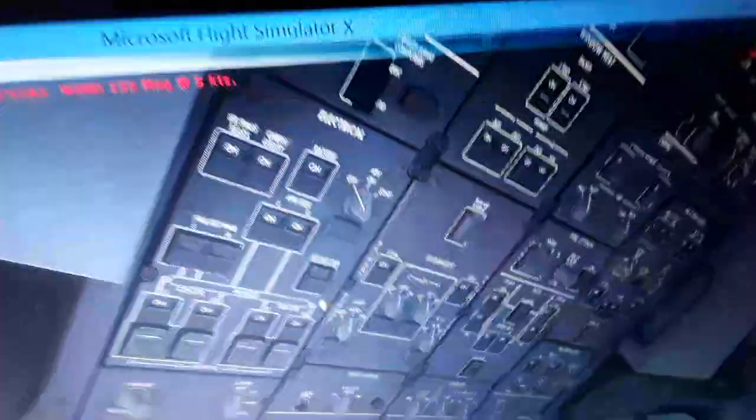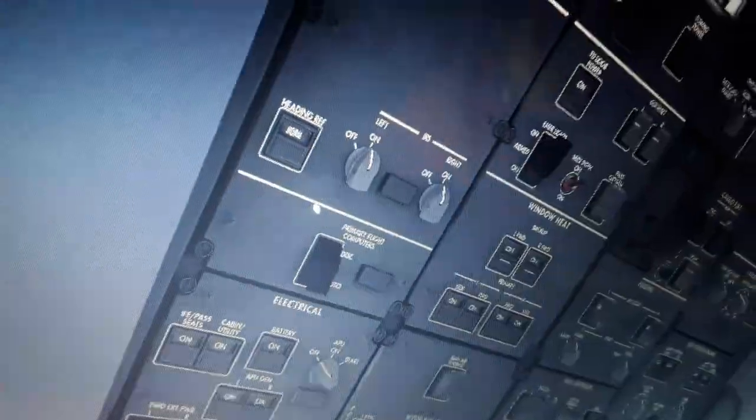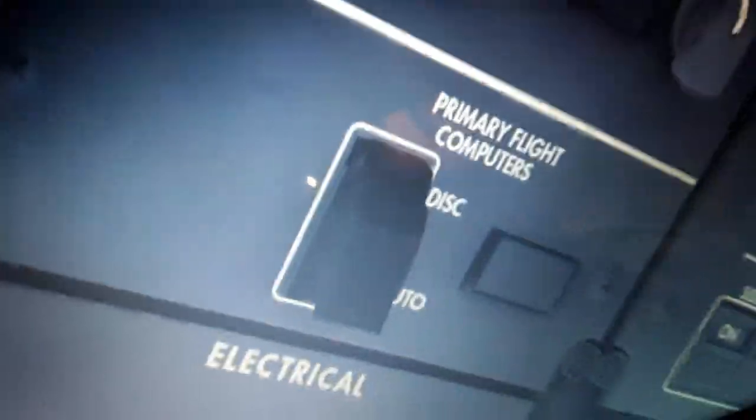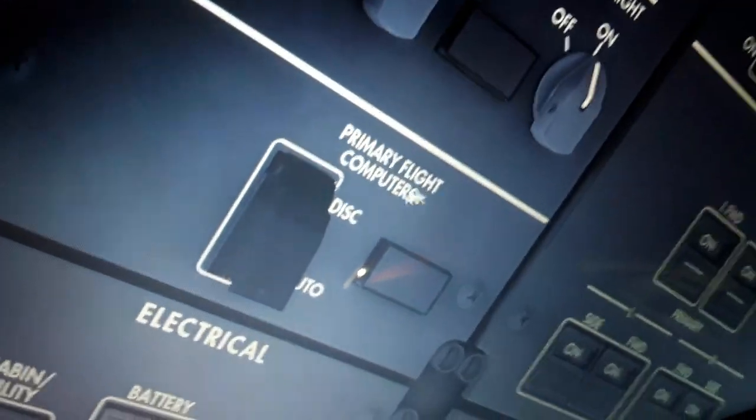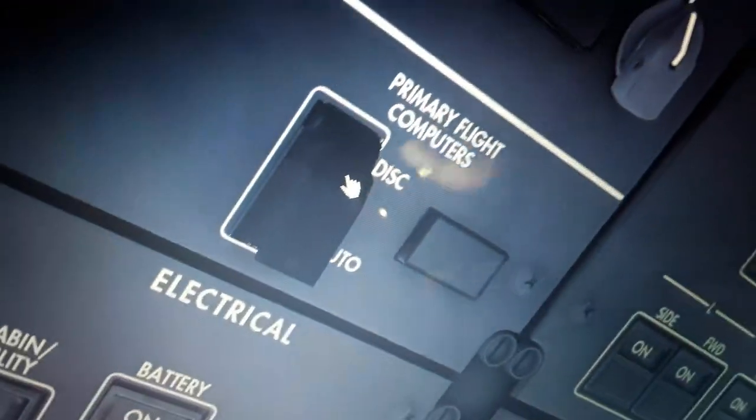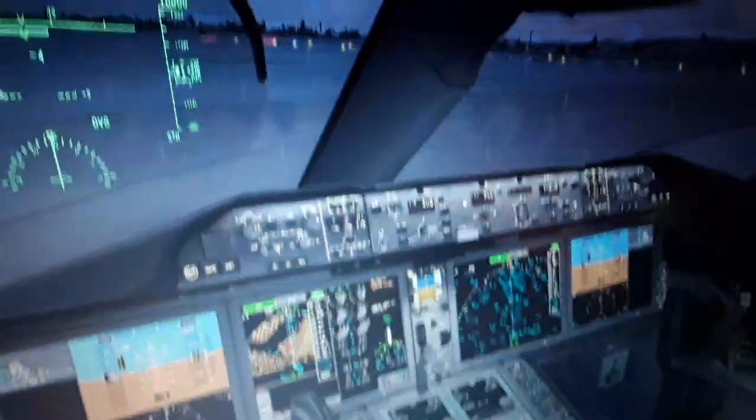So you have the flight control computers over here in the normal, in the auto position. Primary flight control computers control all the flight controls of the aircraft, like in the Airbus aircraft, in the Boeing 787 and 777. You have load limits, Z turns: like in the Airbus you have 2.8 G in left and right turns, so 67 degrees maximum bank allowed. Also in the climb you have in the Airbus 30 degrees and 1.5 G in climb, and minus 15 degrees or minus half G in descent, and other limits and protections.